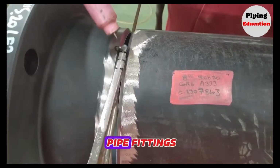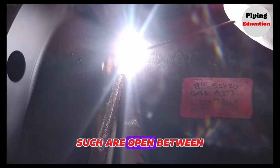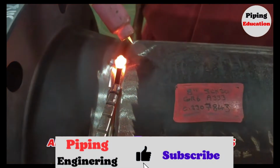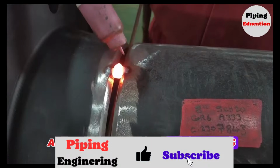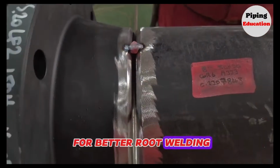During fit up, there should be a gap between pipe fittings of approximately 3 millimeters, it is for welding. You can see this gap for welding now in this video. During fit-up, such gaps are opened between the pipe fittings to be welded, a gap of approximately 3 to 4 millimeters. Having this 3-4 millimeter gap is for better root welding.